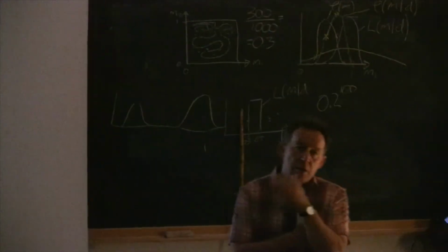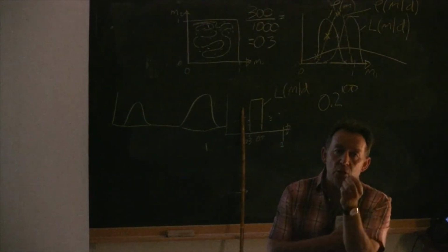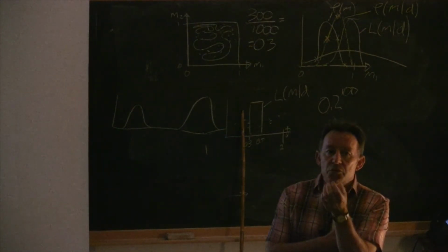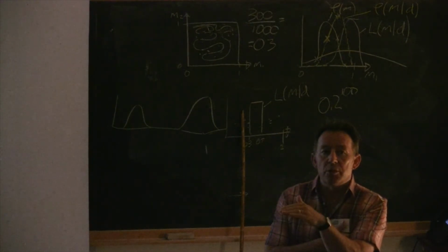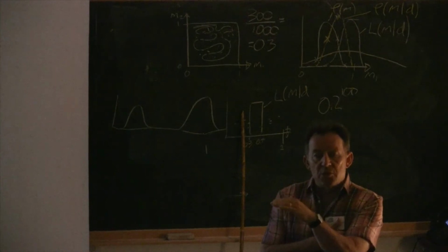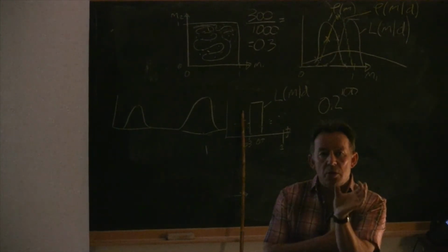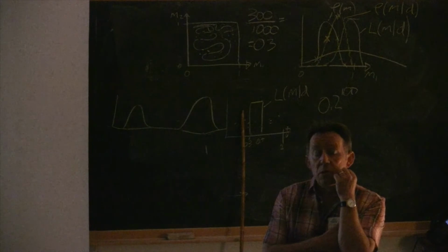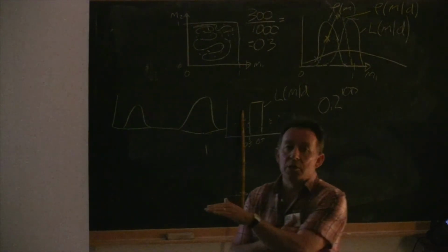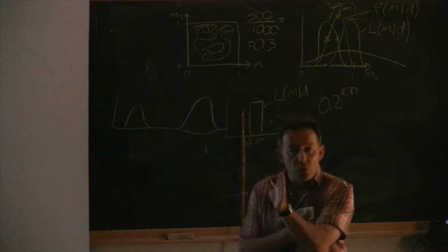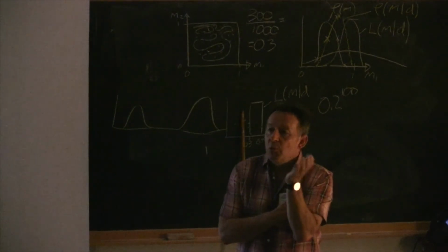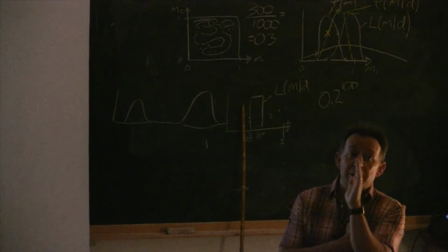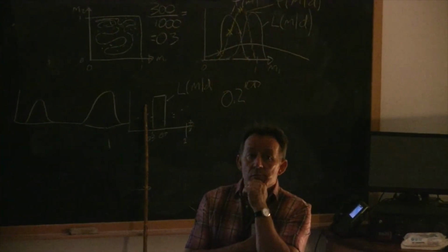One thing I've labored for a long time is that you need to quantify your measurement errors and you need to quantify your model errors. In any inversion process, you need to understand what the appropriate stopping point is and have an objective measure for it. If you assess the errors in your measurements and in your model as much as you can, you have an objective way to be at the right level and not be overly optimistic or pessimistic. Other people will have different approaches, but errors are remarkably often ignored with these geophysical surveys.